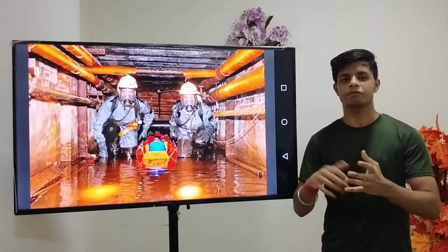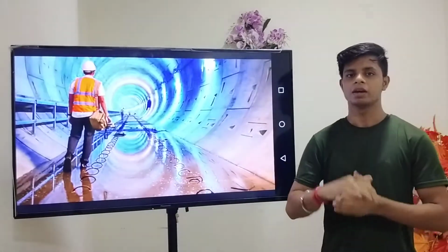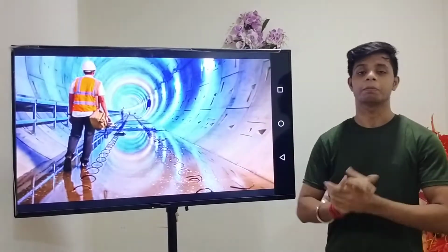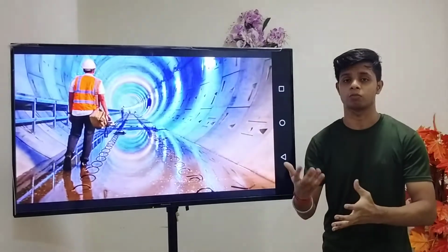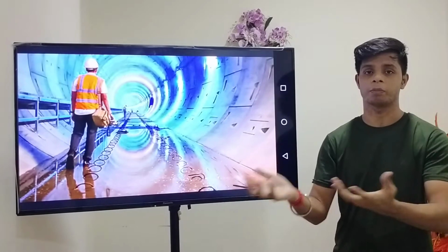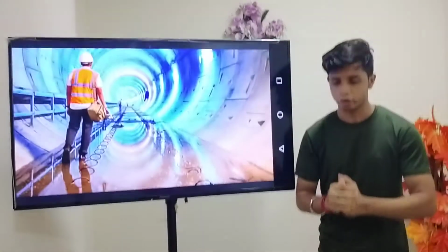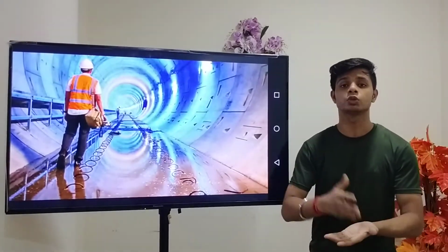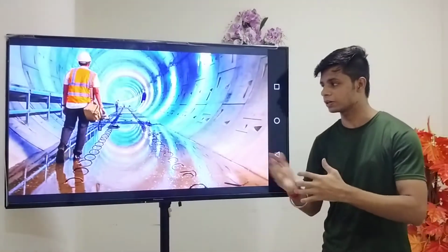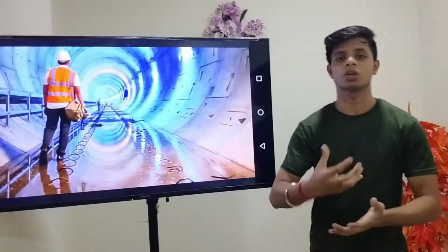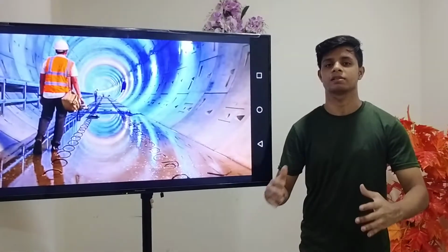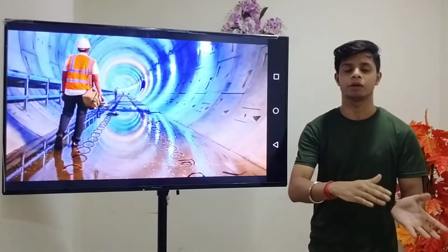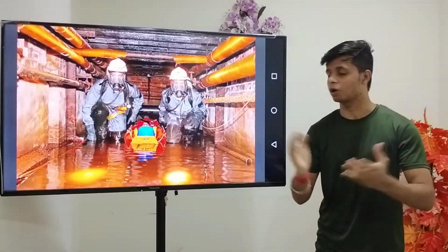After completing our proper work, we need to make sure that we have done housekeeping over there, because if housekeeping is not proper, or if the latch as well as the hole cover is not properly installed, then there may be chances that some children or some animal can go inside. We also need to make sure that whatever electrical equipment we are using inside that confined space meets the criteria, because as you know, sometimes flammable vapors may be present inside. At that time there is a potential for ignition. If ignition occurs, that is the worst thing that can ever happen to you. So we need to make sure of all these precautions before taking entry inside the confined space. So this is about the confined space, guys.